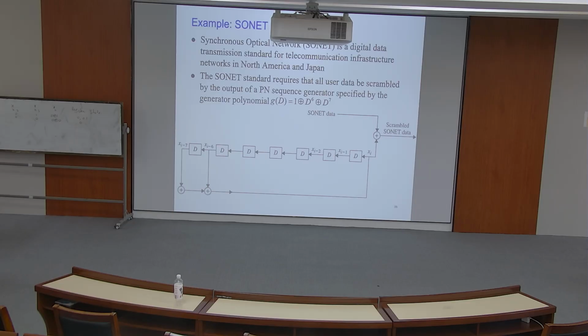So the maximum period of the PN sequence in this case would be how much? Here, how much would be the PN sequence? This would be 127.